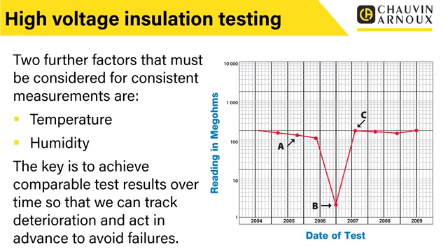That's then followed, at point B, by a catastrophic dropout. So we've seen a gradual deterioration over time, which potentially we should have identified as part of our preventative maintenance and kept an eye on. That's then led to a catastrophic drop in insulation, at which point something's had to be done. At B, it's had to be a repair, or something's had to be replaced.